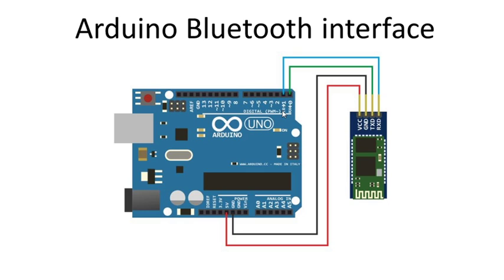Then after that, you have to connect VCC with 5 volt and ground with ground. So that is very important, and these are the 4 connections you have to make, 4 pins you have to use on your Arduino. If you did it, then your connection is complete.